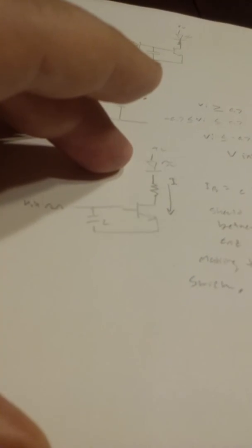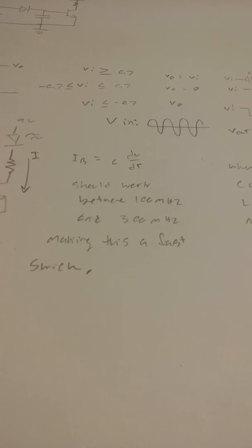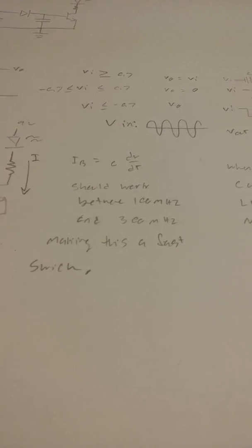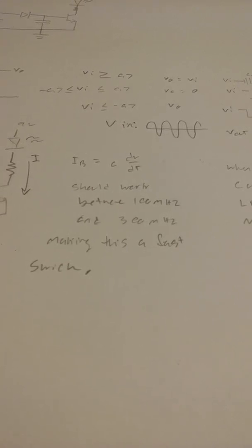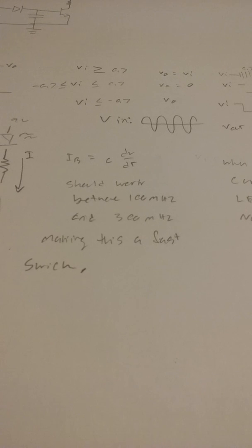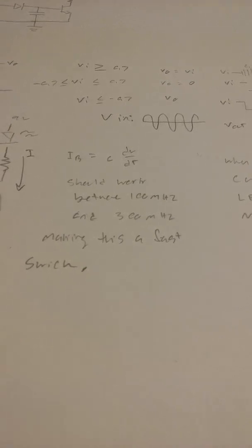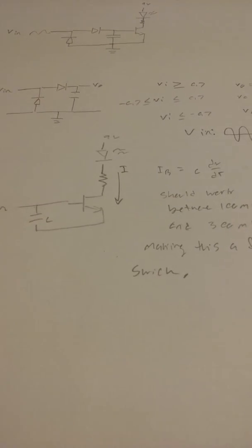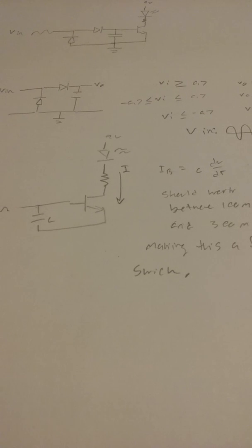The LED will be flickering on and off at a relatively high frequency, so we won't be able to see it flicker on and off, but it'll look like a pulse width modulation or bit angle modulation, where the LED is flashing at full brightness on and off, but only for a moment. I didn't do a DC or gain analysis on this transistor, mostly because it doesn't matter.